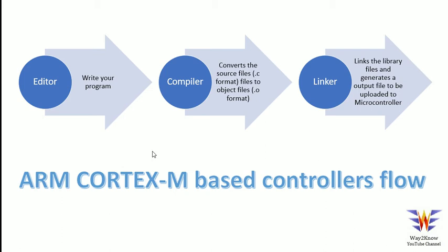IDE means the Code Composer Studio kind of environment where you write your program and then use the compiler. That means when you build, when you compile your program, that compiler converts the .c files, whatever you have written, into object files format.